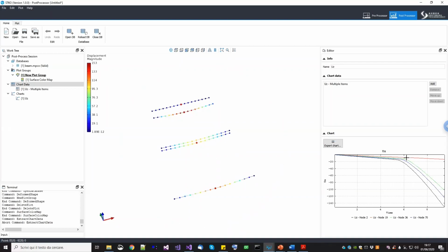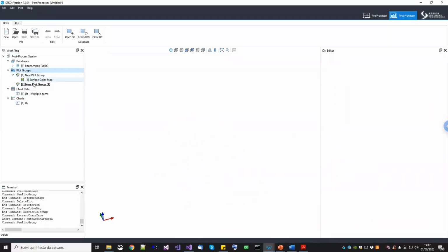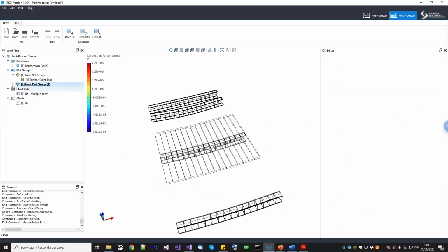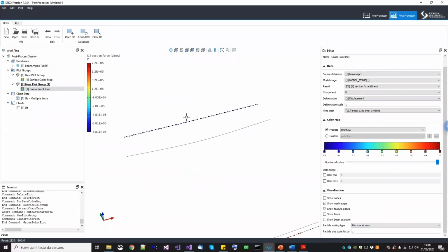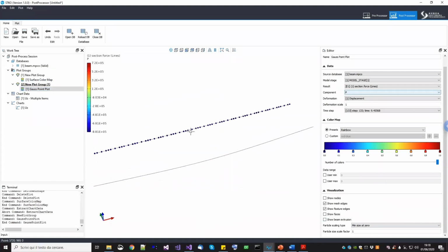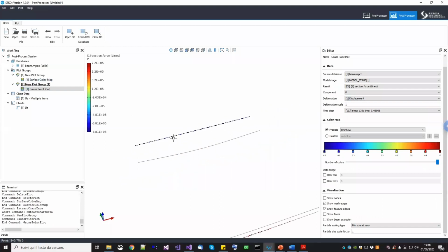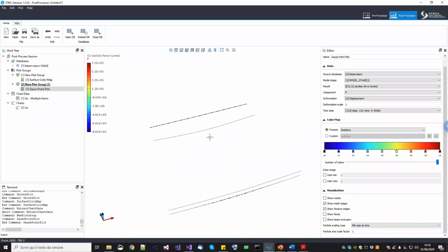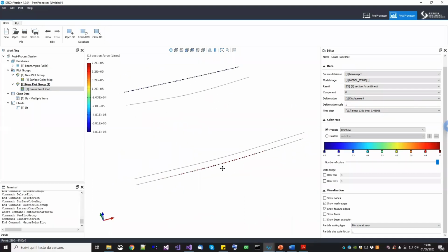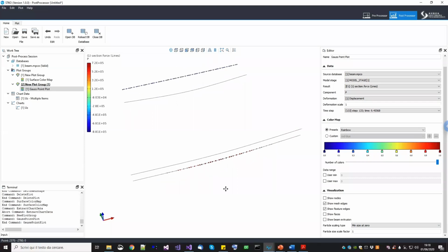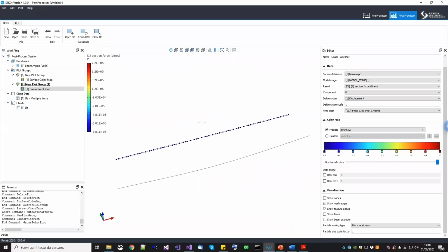This is happening because basically this one with the axial curve has very high compressive stresses. So if I go here, for example, and I change the plot group to a Gauss point plot, as you can see, when I plot P, so the axial stress, only this beam will have very, very high axial stress. This one will have actually 0. And here you can see something, because in the real solution, the axial stress is not exactly 0, but is much less than these values, okay?